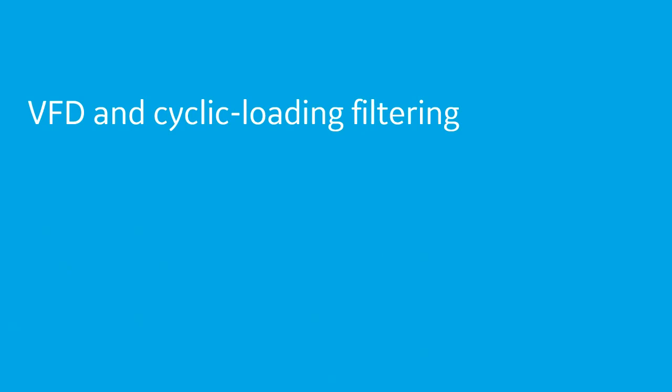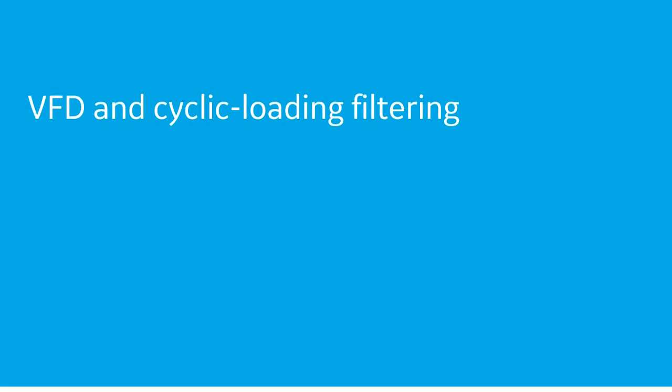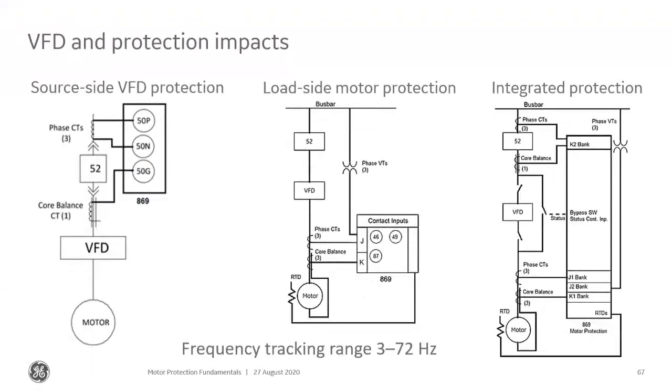Okay, so I want to talk a little bit about variable frequency drives and cyclic loading filtering. And this was a question I think that Eduardo got in the email advanced questions. So there are some options for your VFD protection. You can set your VFD protection on your source side, and in this case we're going to look at your phase overcurrent, your neutral overcurrent, as well as a ground overcurrent going into the VFD.